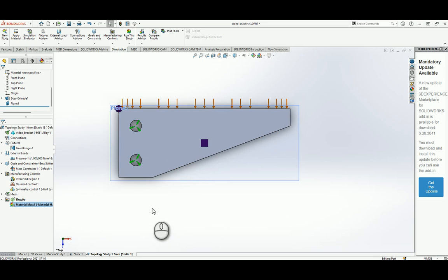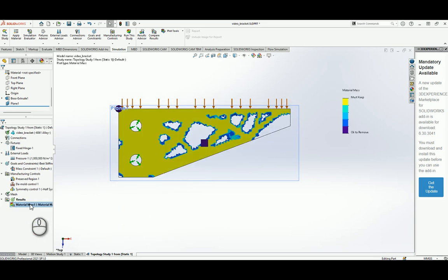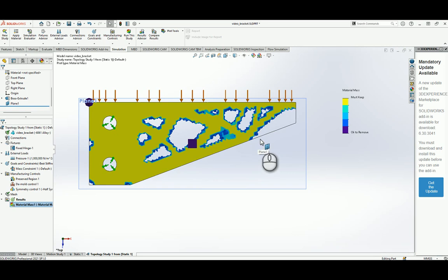Essentially that will create a body with jagged edges like this. So unless you want to 3D print this thing, and even if you want to 3D print it, you want it to be a lot neater than this. So what we could do now is use some of the tools that we customarily use in SolidWorks, your drawing tools, so we could draw over this. That way we could physically cut out the material that the analysis is saying that we could cut out.